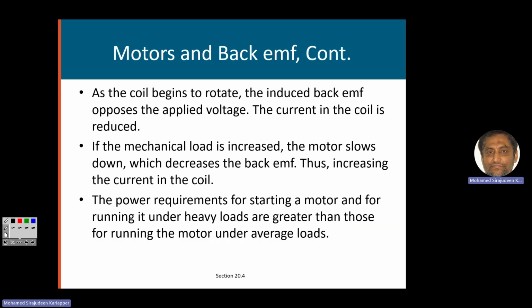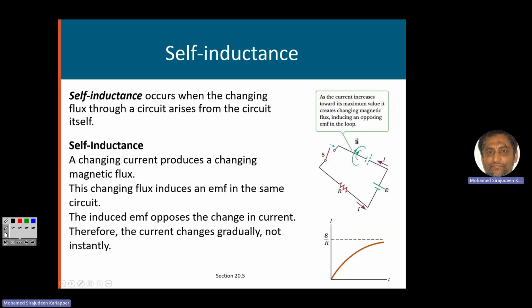So this is why there is a power requirement for starting a motor, because at the beginning when you start there will be a big current, so the power requirement is more. When you start the engine, we need power. And also under heavy loads, the power requirement is more. Heavy load means it rotates slowly, that means back EMF is less, so the current will be greater. So again, the power requirement is more compared to an average load.